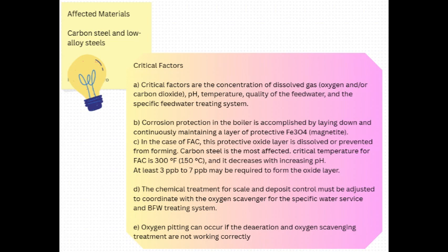And the surface looks kind of scoured clean, no magnetite scale left. Often you can even see flow patterns etched into the metal. And the danger is rapid, widespread thinning in that area. It's not a tiny pit. It's a larger zone losing thickness fast. That can lead to a sudden, catastrophic rupture of the pipe.